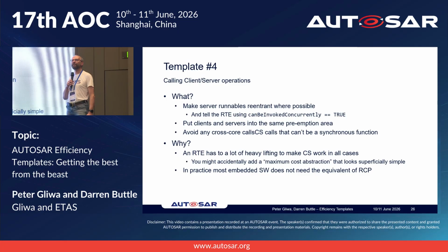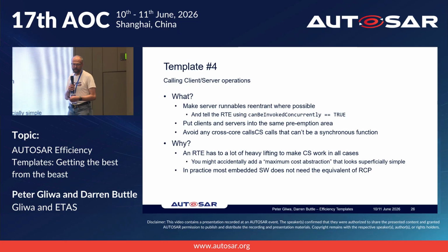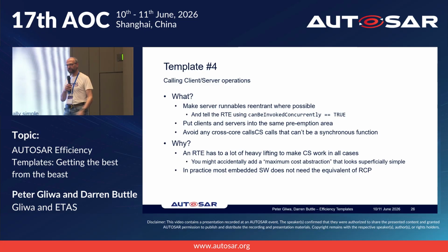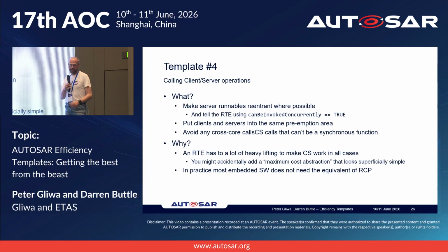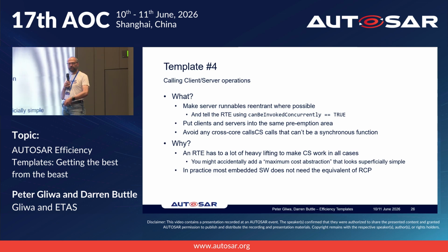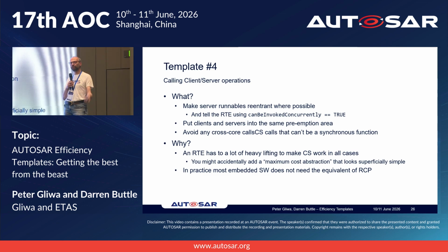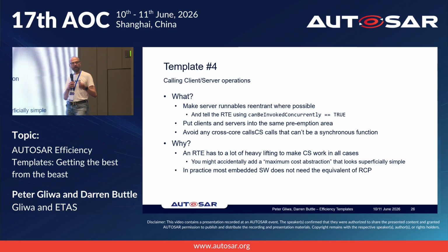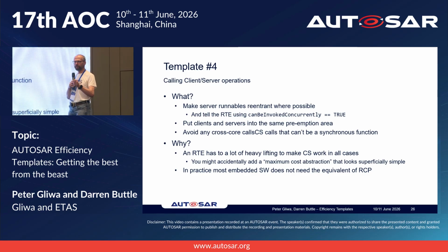Got some data from a very early AOC conference about that. Because you've got to set up the stack, you've got to queue messages, you've got to buffer things, and that's okay. So in practice, you might accidentally stumble over this. If you're not careful about how you do your configuration, you might find that the RTE is doing a huge amount more code and data management work because you've not quite told it enough information on which it could actually make a much more optimal implementation of that.